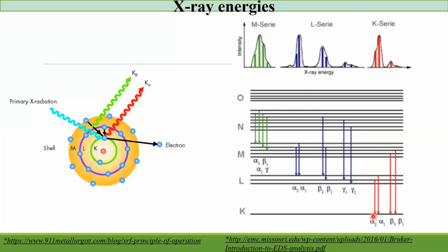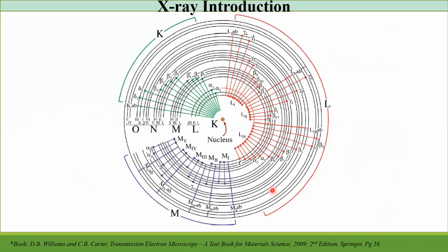So this is from K alpha 1 and K alpha 2, because of the different energy lines within the L, and from here it is K beta 1 and K beta 2, such that every atom and every line has its own alpha lines, beta lines and gamma lines. So you need to think over all this before analyzing EDS. It's more complicated from the perspective of the energy arrangements of the shells. All the lines have all types of energies. So don't go for automatic peak identification in EDS.